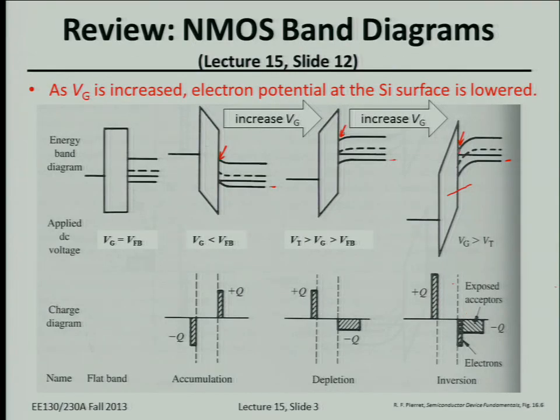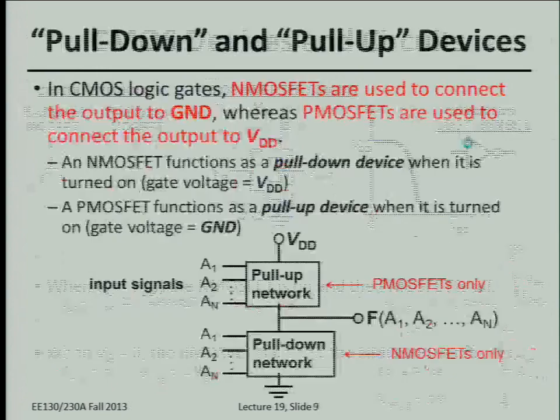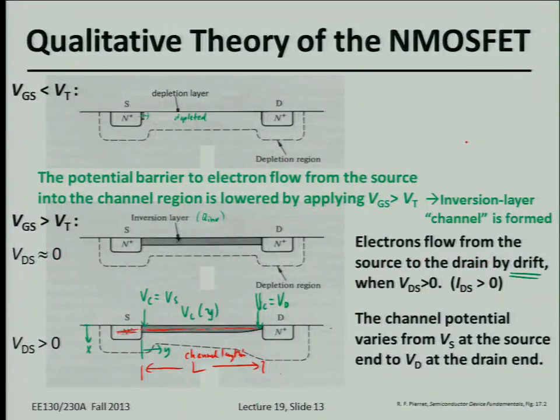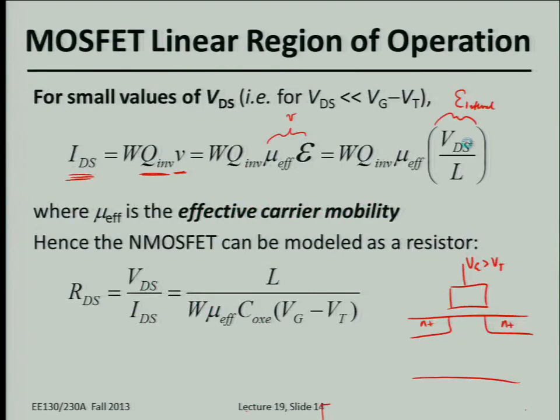When you form an inversion layer, there's this high electric field, with steep band bending at the surface. That causes electrons to be attracted to the gate oxide interface. So as the electrons are drifting from the source to the drain, they're not just scattering as normal. They're bumping into the gate oxide very frequently. People have estimated it could be on the order of terahertz. Because of the strong vertical electric field, they're basically bouncing off that interface. They're attracted to the interface, scatter off it, move a little bit to the right, get attracted to the interface again, and so on. So they scatter off the interface quite a bit.